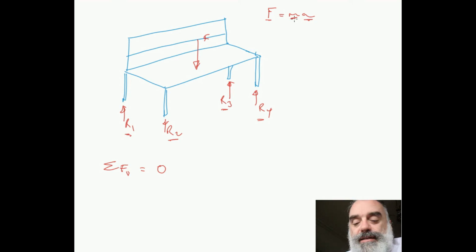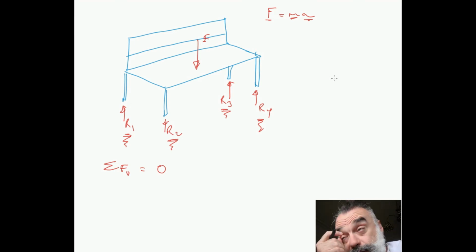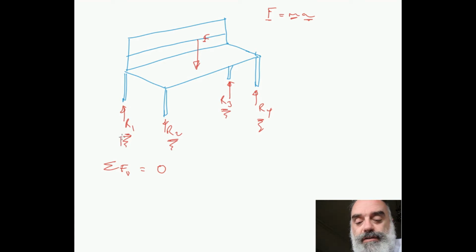And what would happen in that situation is if this force was too great for the ground to be able to react it, if the ground was too soft, then the ground has some variation in the force that it can react with depending on its compression. And again, we can model the materials, and we'll come and talk about the model of the materials, and we can model those as springs, and we can model those as linear springs. So we can assume that the ground, which it doesn't, and we'll come on to that, but we can assume, for the purposes of a simplified model,